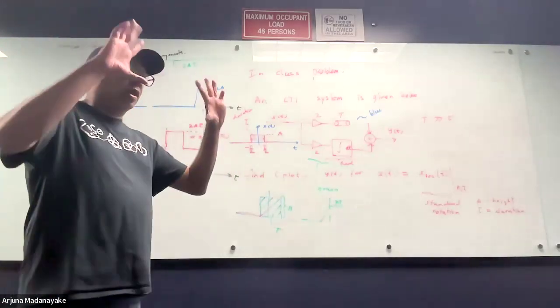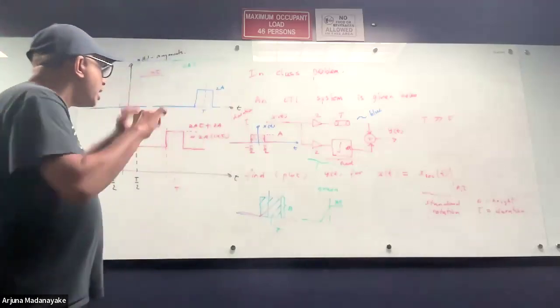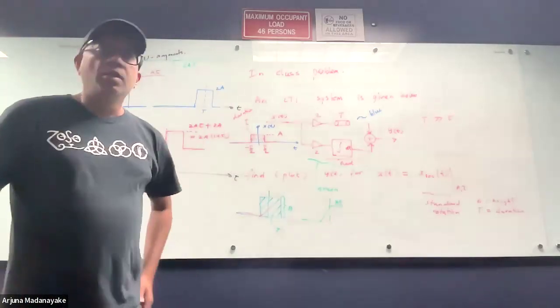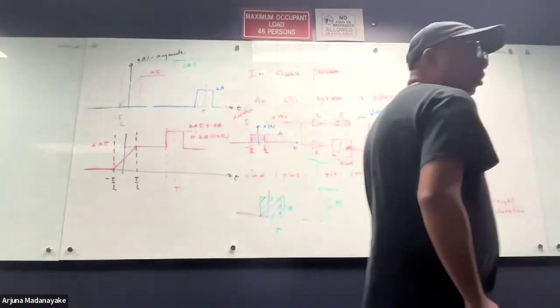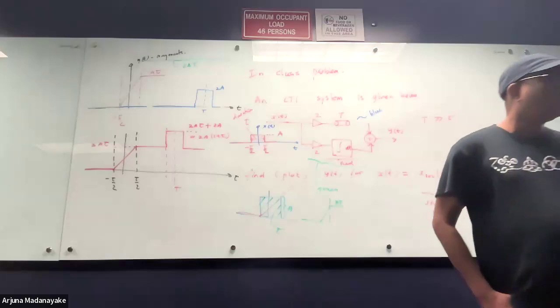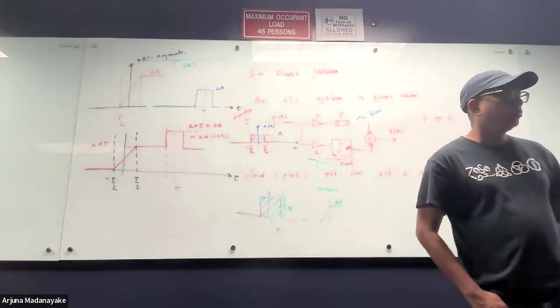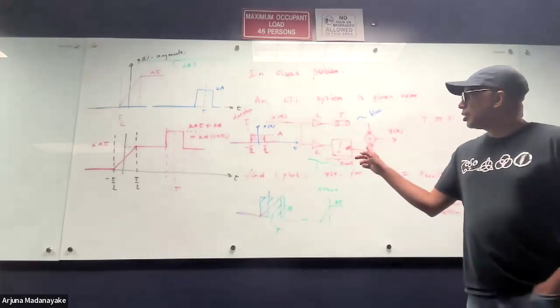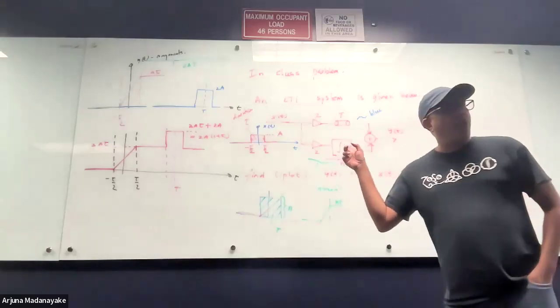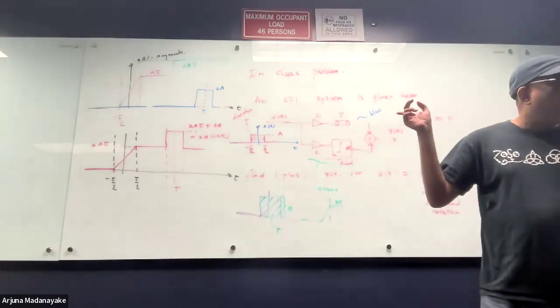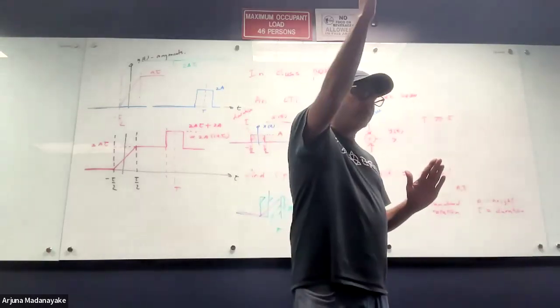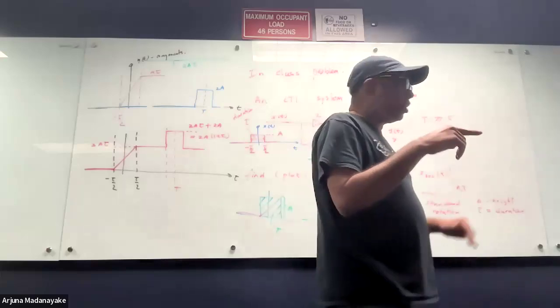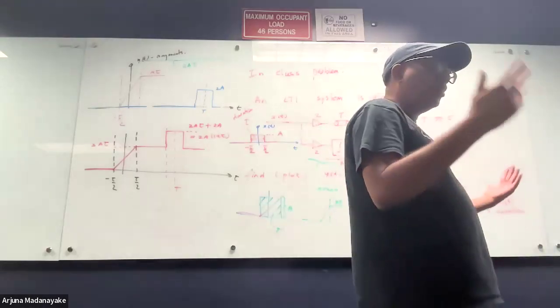You can delay it. You can integrate it. You can differentiate it multiple times over and sum them up. So the integration basically turns it into a linear line, because the pulse is rectangular, right? When you integrate a rectangle, it linearly increases. But depending on what the input is, the integral function looks different.